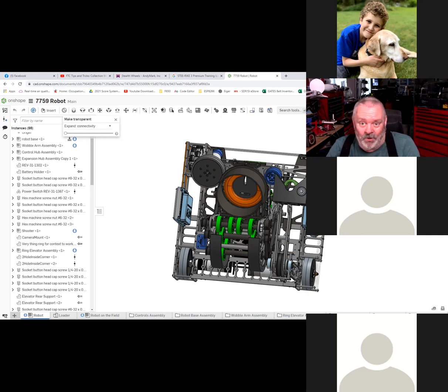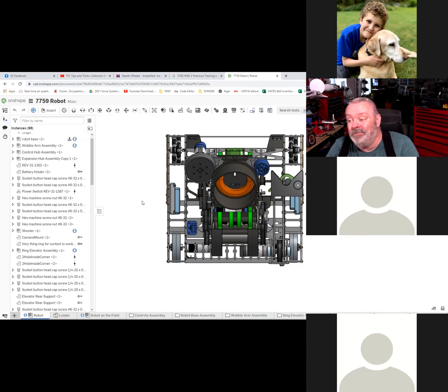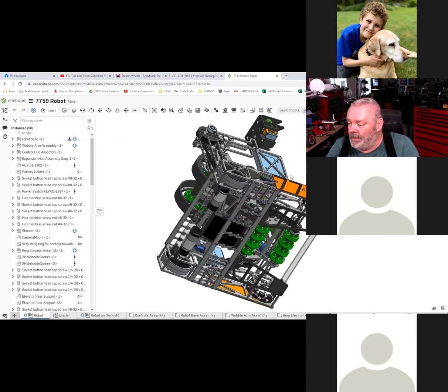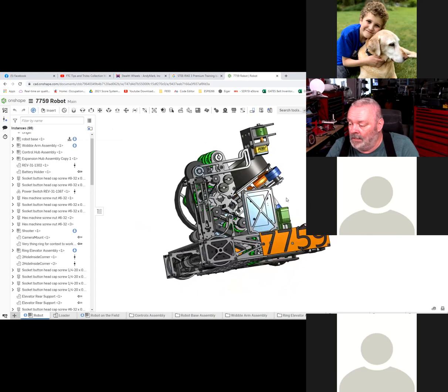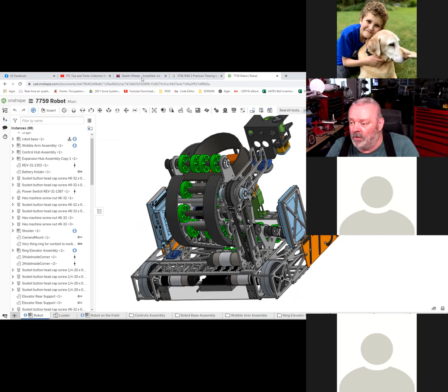So like Karin is pointing out, there are downsides to these wheels. They have no coefficient of friction in the perpendicular directions, right? So they do fine if you've got a motor on these. They actually do fine going this direction, right? So going straight ahead, coefficient of friction is not bad, and they're drivable. So again, just an option, there you go. That's called an Omni wheel, OMNI, and you can find those on.